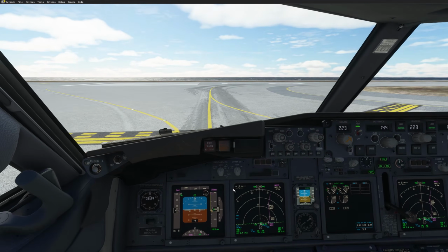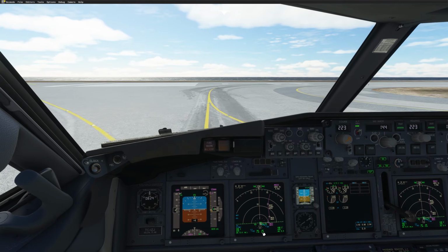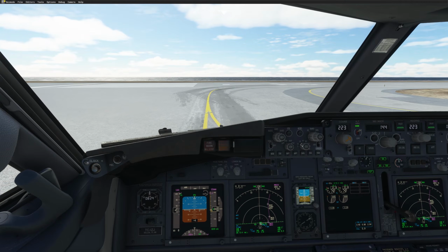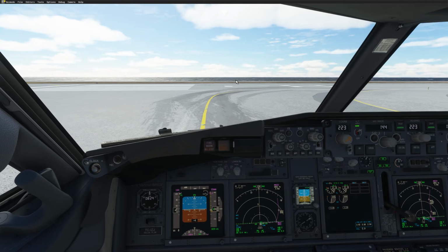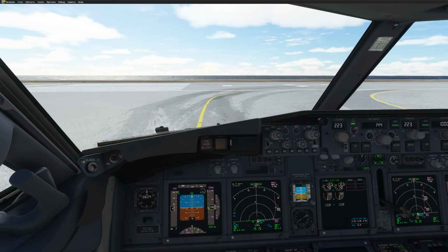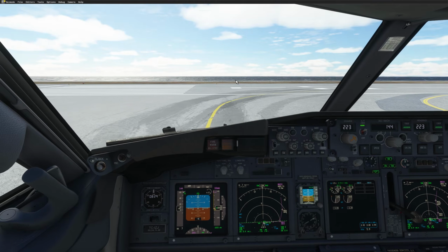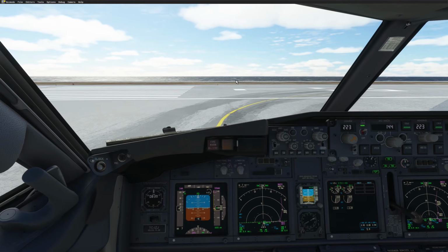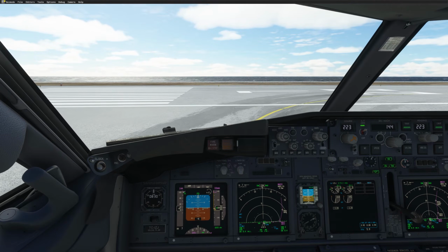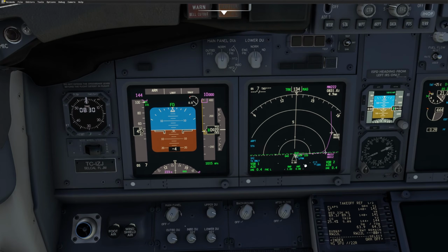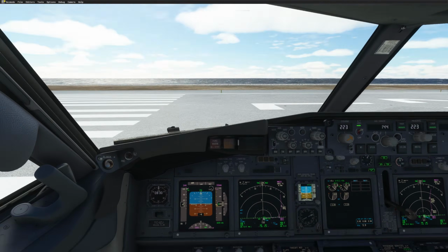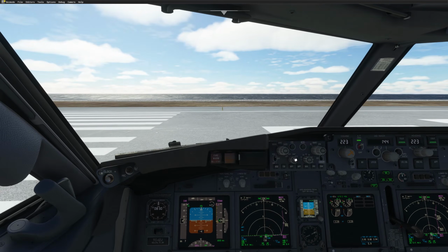Now it's important to check that you have auto throttle armed, that you can see your departure line is correct. Otherwise, sometimes that's as well a good reminder that you might not be in the right place, or that you didn't put the right runway in the FMC. So here everything looks good. The deviation is 0.00, so that means I'm where I'm supposed to be.